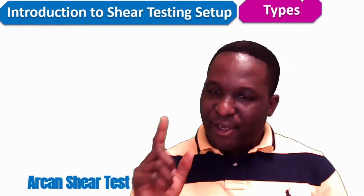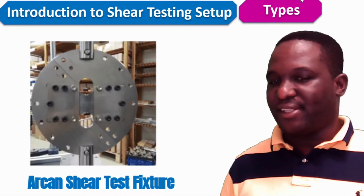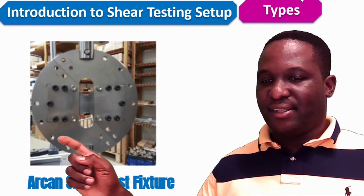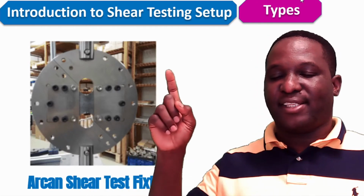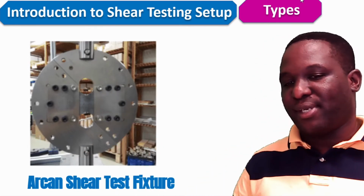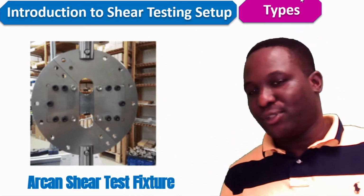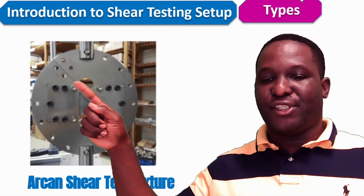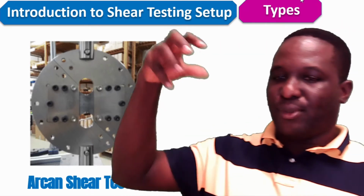Okay, what about the fixture? How do you actually do this? The fixture for doing this looks like this. I've taken this picture from a publication again. Like I said, this part is going to be fixed, and the other part is going to be in motion. This end and that end go into the test equipment, so that as you begin to pull it out, one end is fixed and the other half is able to move. And the regions around here and there are where this Arcan fixture is broken, so you can always pull it apart at that point.